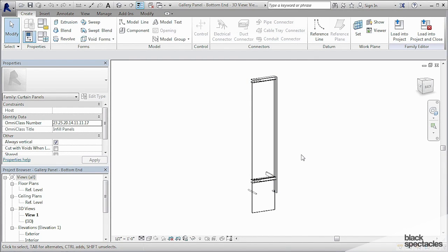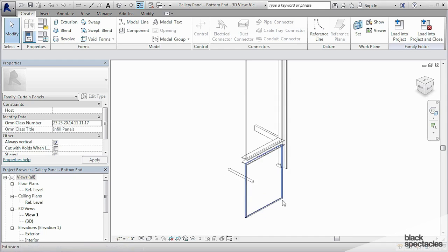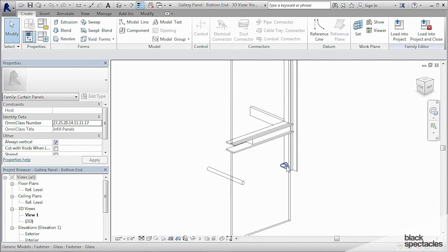So essentially what the design of this curtain wall does is it has this overlap and this sort of fin that just sticks out here in space along the bottom, and then on the side it just has this piece of glass that just extends out, and there's no building or anything, no enclosed space behind it. And then the only other difference is the fastener on this side just connects back to the building like so.